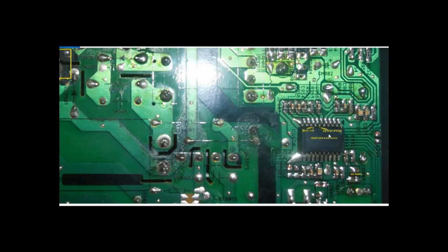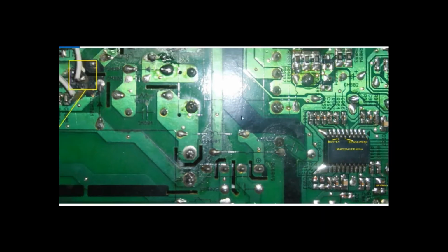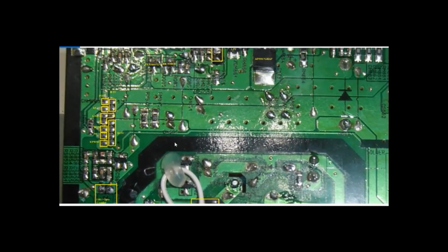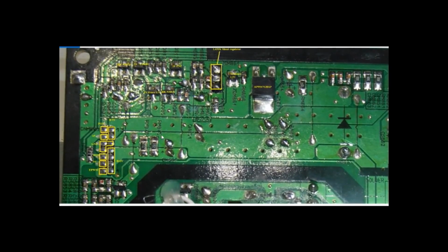As I explained earlier, the EPWM signal is directly sent to the 7th pin, and with that it controls the brightness of the LEDs. And this is the backlight on signal. We need to make sure that the backlight on signal is given to the 8th pin, so that it starts switching on the backlight. We pretty much understood what is in the connector.